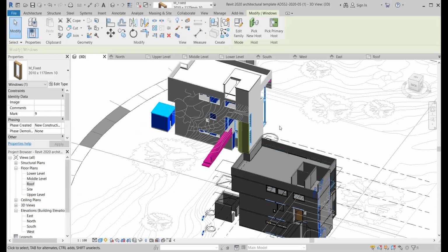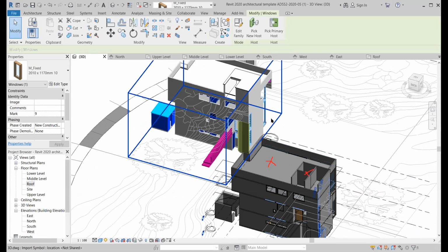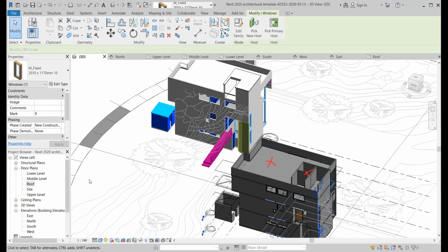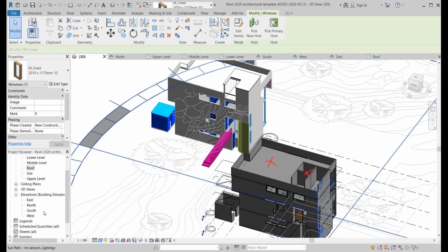So basically, you need an additional level, because here we have the floor, the roof, the main one, and after that we will need the second roof. You call it roof 2 or something, which means you have to go to the elevation and you create another level. Elevation. How to create another level? Come on, you did all this and you don't know how to create another level?